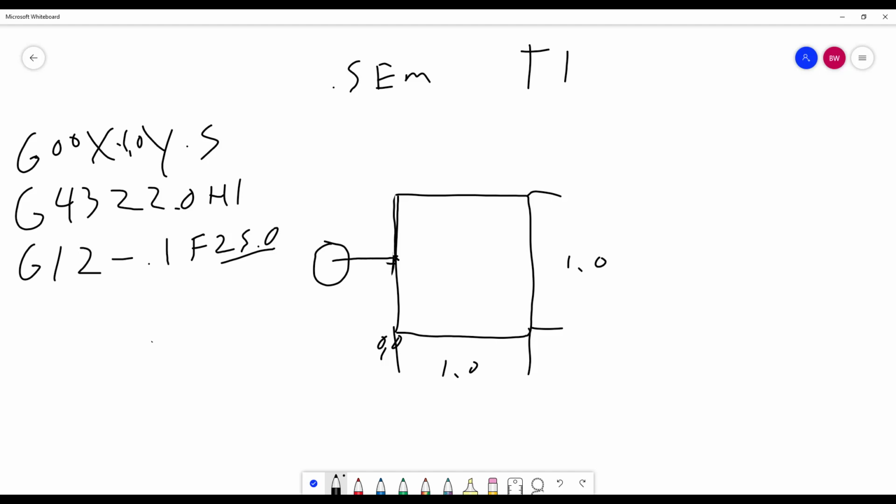We're an inch away, the half-inch cutter, we've got plenty of room. Again, in our case, it is going to be at least the cutter diameter, and it's technically at least the radius, but we'll go with cutter diameter or more. If you're only compensating for 5 or 10 thousandths, and you are actually numerically offsetting the code, like I showed you in that first example, where you can actually compensate the actual G code for the end mill radius, you do not have to lead in as much.